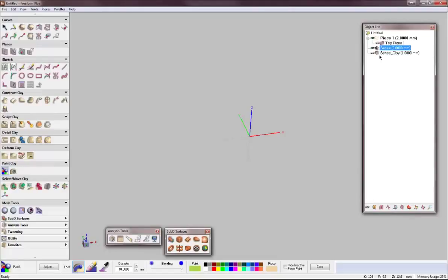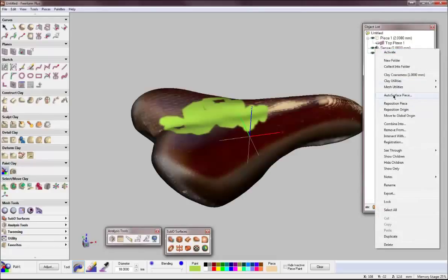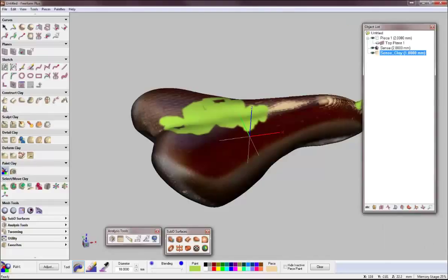We also do have a tool inside of here where I can take a clay object and auto-surface it into a NURB surface, and that will dump inside of the CAD package of choice, and you can use it. Now, it's not going to be a parametric model, so things like booleans and cuts and merges and things like that will all work on that surface body, but it will not have a history tree that you may be familiar with if you're using that type of device.